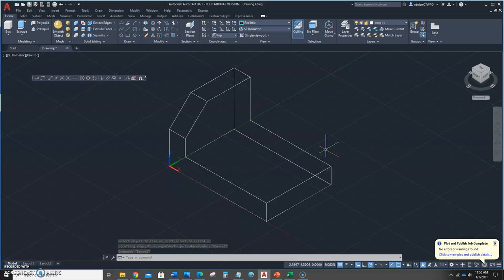I'm going to take now and offset this line here, for the little cutout in there. Now the thing is, right now that is a single line. So if I go to offset that, and I offset that like 0.5, what's going to happen is it's going to offset that whole object. That would be fine if I had to go 0.5 here, but I don't. So what I need to do is explode this into the entities again. Now one thing that's tricky here is that this line and that line are lining up.